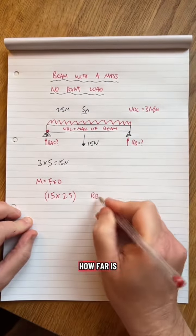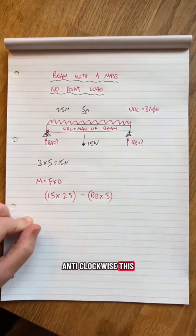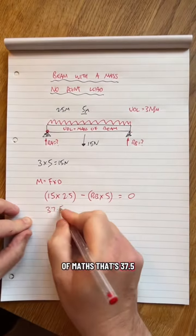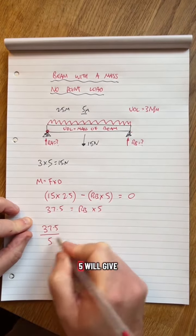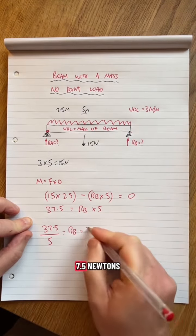We're going to one more force. RB is the reaction. How far is RB from my pivot point? 5. Which way is it going? Anti-clockwise. This beam is balanced. All add up to 0. Do a bit of maths. That's 37.5. Bring this across to make it positive. RB times by 5. So 37.5 divided by 5 will give me RB, which gives me 7.5 newtons.